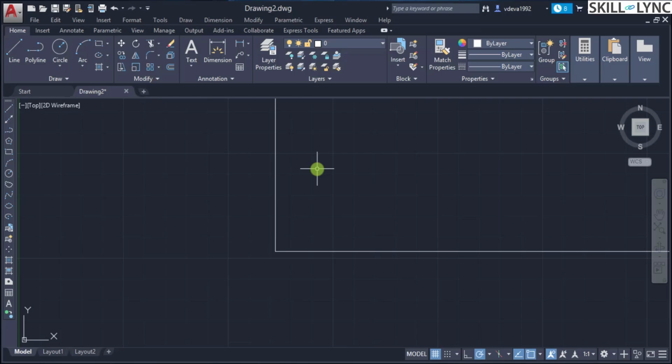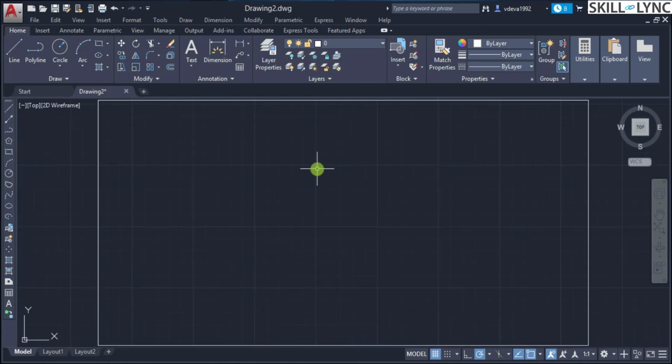So next, the command is zoom to extents. We'll try it out directly here. It means that it will zoom to the largest possible extent that is available with the objects. As you can see, we have zoomed to one of the corners of the object. Now let us invoke the zoom to extents. It is invoked by typing the letter E as the first one. Once you press E, the zoom has been applied to the extent of the current object that we have in hand.